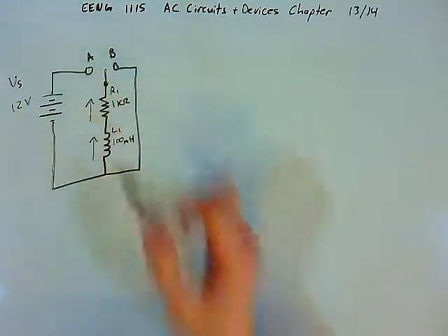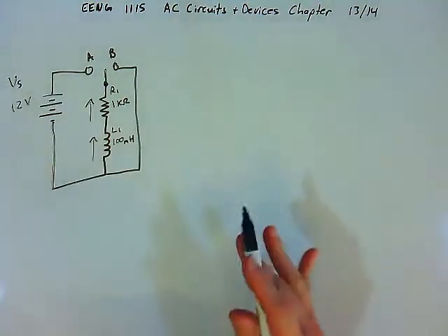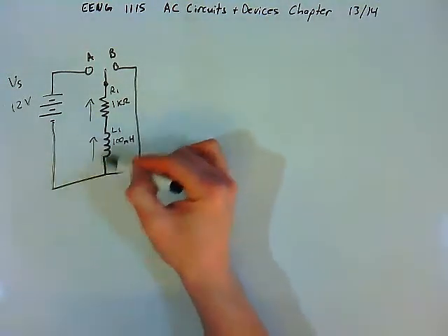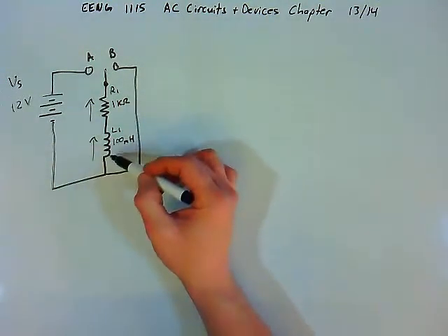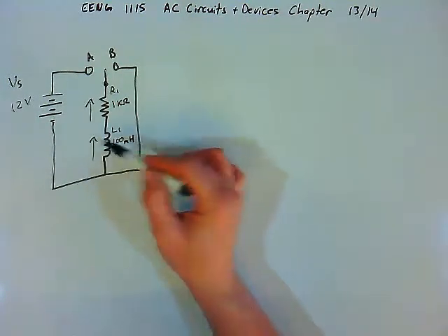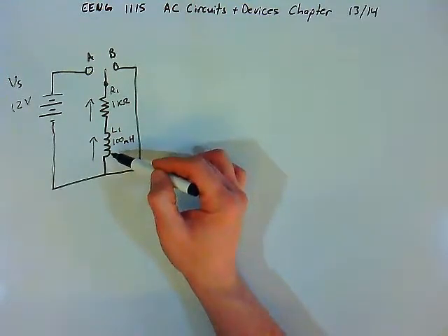So when we flip the switch into position A, the current starts off as 0, the current starts to flow, and some of that energy is used to induce a magnetic field around the inductor. The magnetic field grows. And so the current doesn't flow at the same rate as it would without the inductor in the circuit, because some of that energy is being given to the inductor to be stored as a magnetic field.